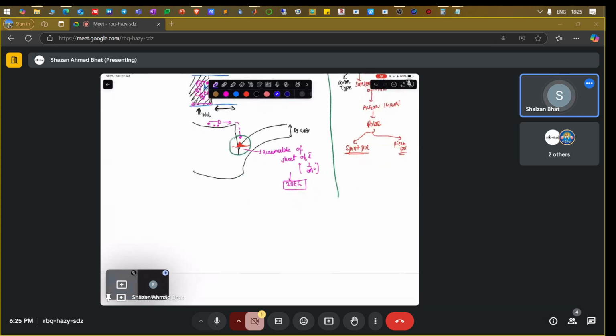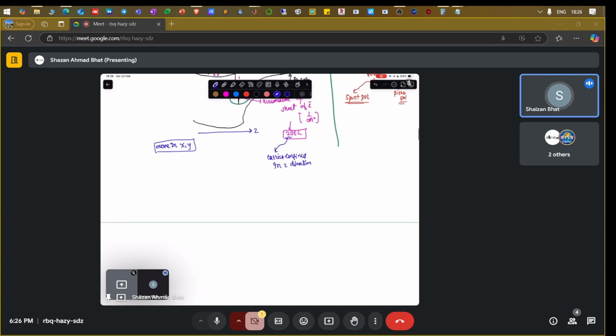I've talked about why it's called a two-dimensional electron gas. It is two-dimensional because the carrier is confined in one direction, the z direction. What does the z direction mean? If this is the z direction, the growth direction, then the carrier cannot move in this direction. It can move in x and in y. And how does that look? Let's say you have a wafer. That is how gallium arsenide or gallium nitride looks. It comes as a circular, disc-like wafer.